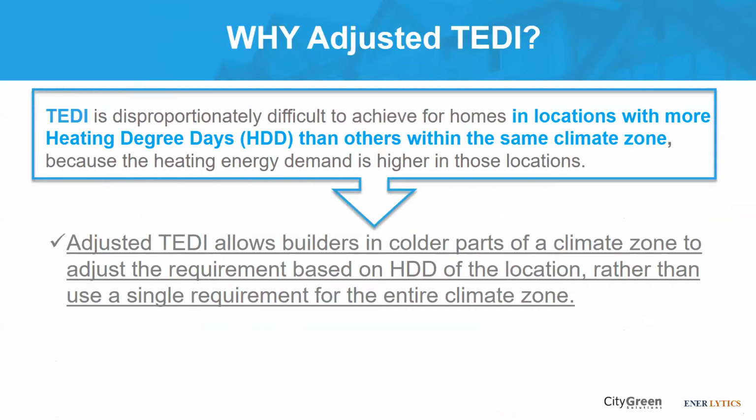And what adjusted TEDI does is allow builders in colder parts of a climate zone to adjust the requirements of the metrics they need to meet based on the heating degree days of the location, rather than using a single requirement for the entire climate zone.